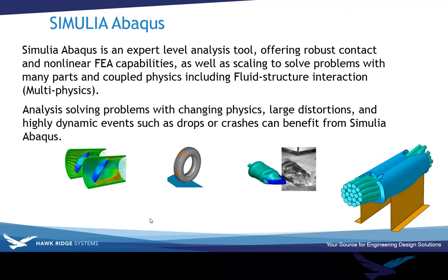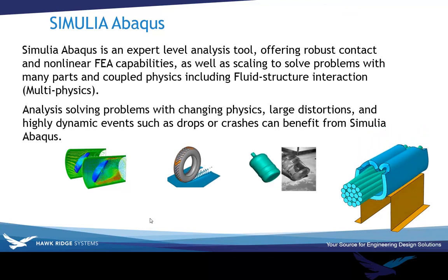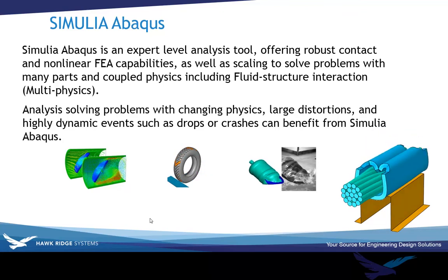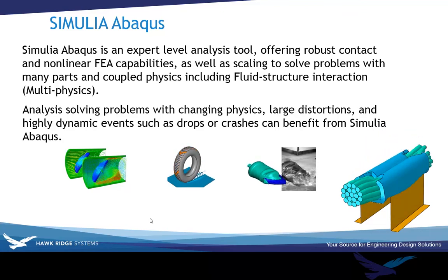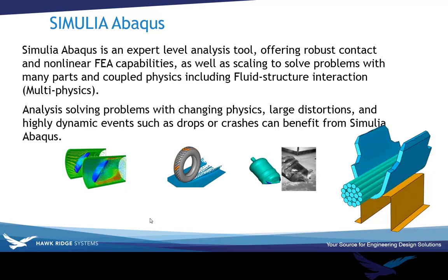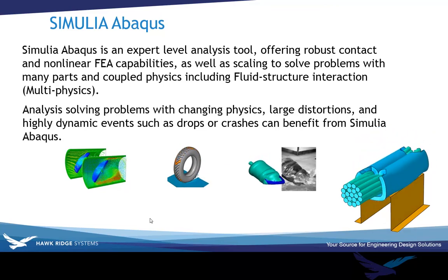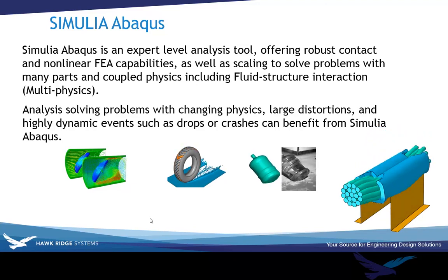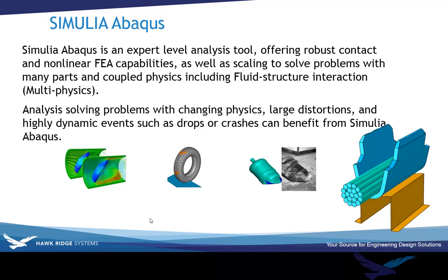We wouldn't really be able to do that within SOLIDWORKS Simulation nonlinear, mainly because there's a lot of contacts that are changing as a function of those different parts, where you're maybe hitting a wall in terms of how much we can manipulate inside Simulation Premium. So this is where Abaqus can really help with these more complex types of problems.